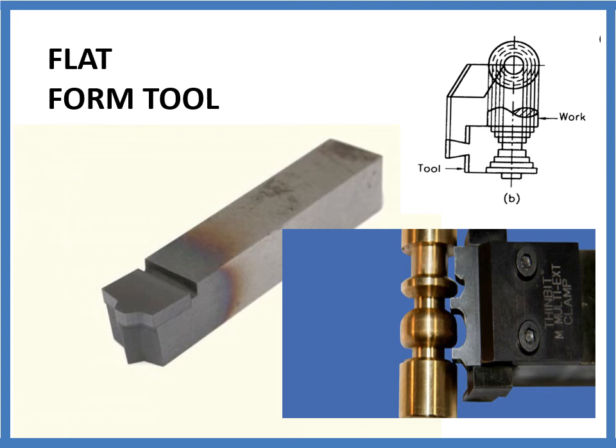A typical example is a V-notch tool or a threading tool, and this type of tool is suitable for making deep straight-sided form grooves, and the cutting is restricted due to the mixed chip flow. Because of the good surface finish they produce, typically these tools are operated at a very low cutting speed.